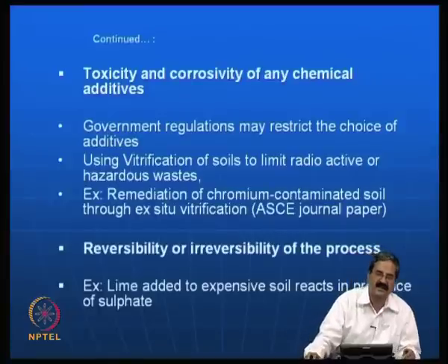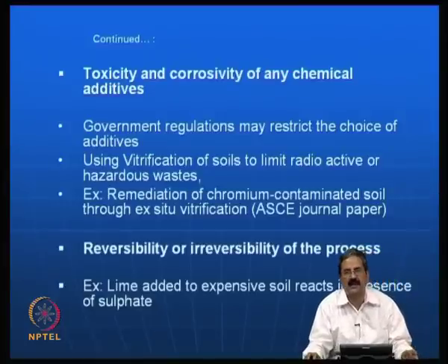In fact, in Texas area, Arlington and many of the places in the US, a lot of roads have got damaged. They initially thought that the Texas area is full of expansive soils, and they thought that by treating the soil with lime injection and all that, they could have this problem rectified. But what they finally observed was that since the soil has sulphate, heave took place and the problem got worsened. Actually, I will show you some of these photos also in a very detailed manner later,